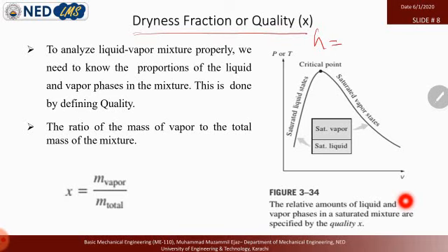If the quality of steam is 0.5, then the enthalpy will be hf plus x hfg. By this equation we get the values in between, inside the wet dome, and in the saturated tables, because at any point here the pressure will be the same.